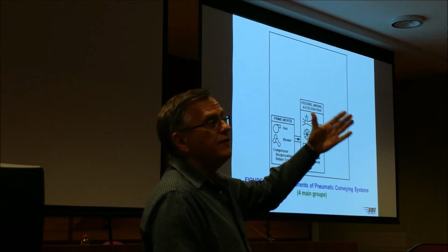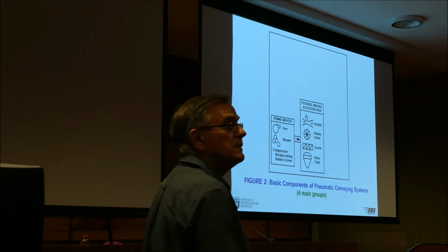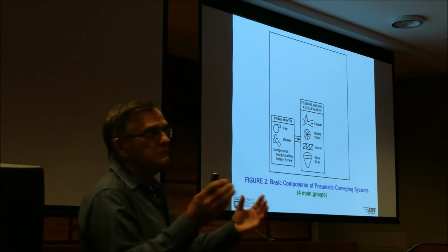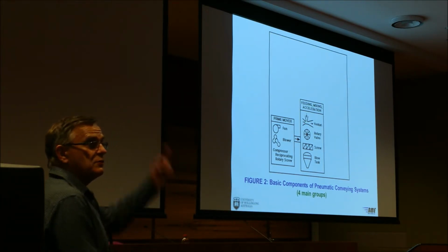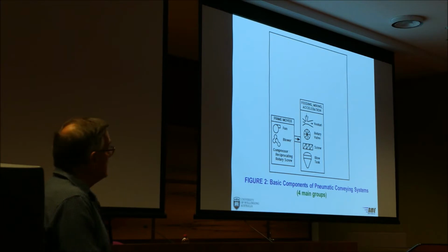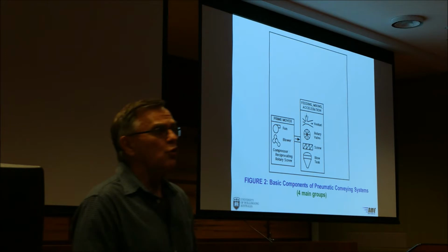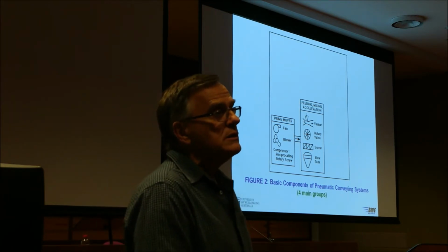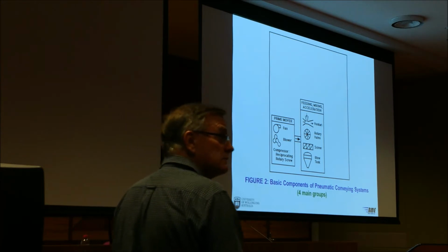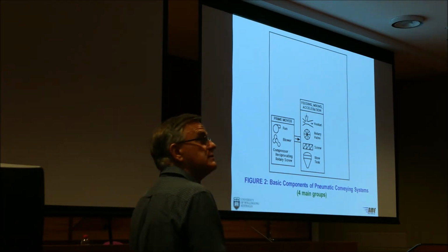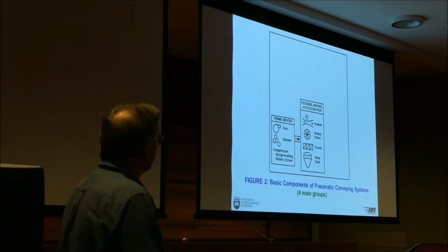But you can only do that up to a certain pressure, typically about 10 kPa gauge here, maximum. Once it goes beyond that, you can't suck anymore at this point, and you blow up the opposite way, which is not good. So these are being used in applications where you've got high temperature or high abrasion, so you don't have to have moving parts. You can make them out of ceramic, so they last a decent amount of time. Not many of them around, but they are out there.